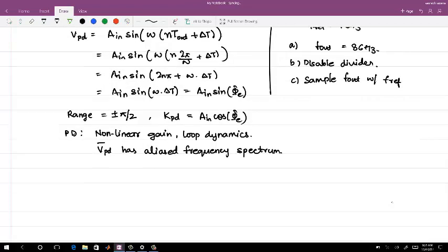So the other thing is this phase error. What is phase error as such? Phase error is a way of representing the clocking instant difference between the reference and the output, right? That is what we are concerned about, that the output should always be rising at a fixed instant, rising edge or falling edge, right?